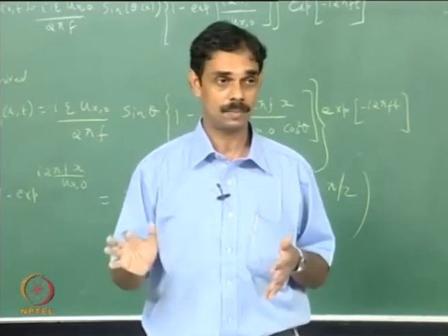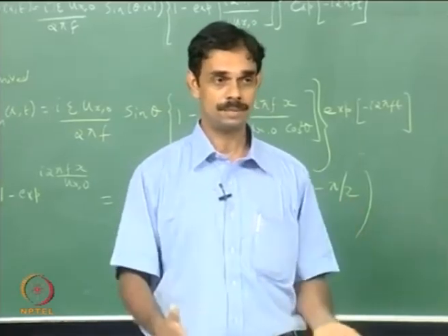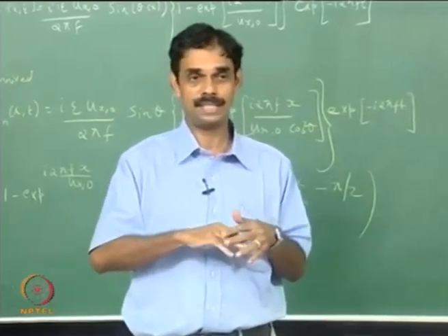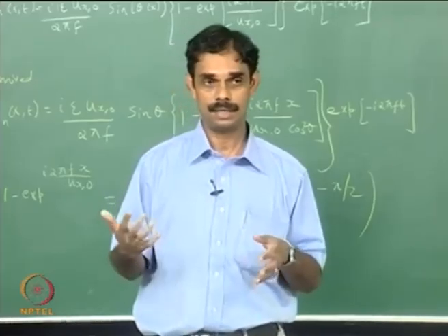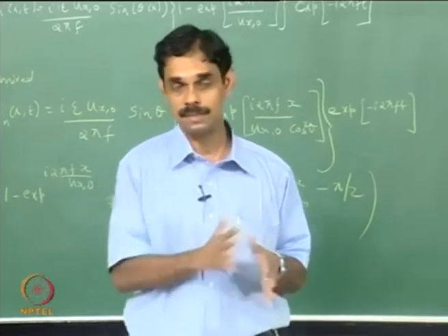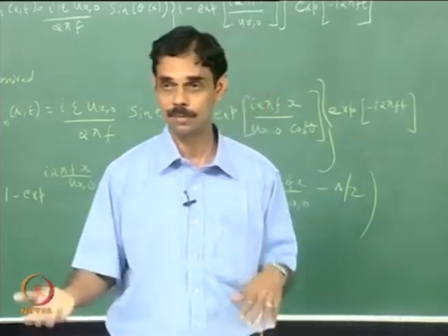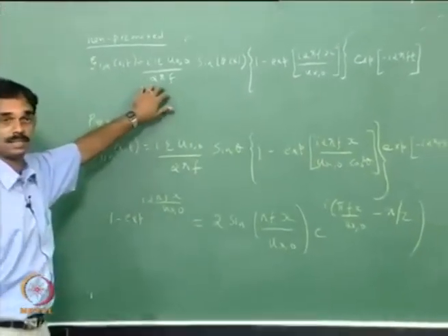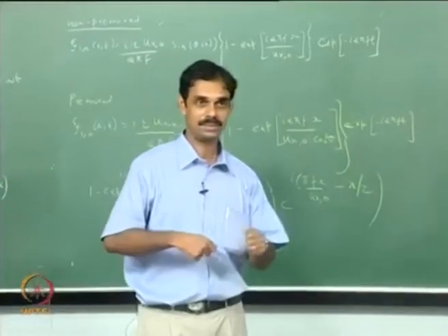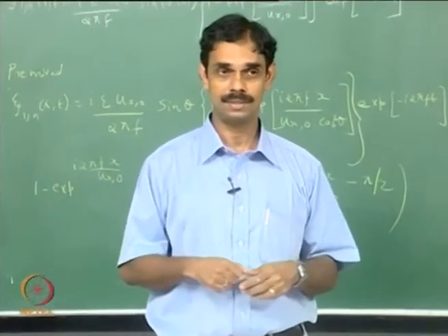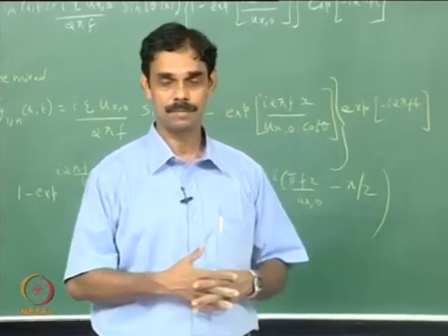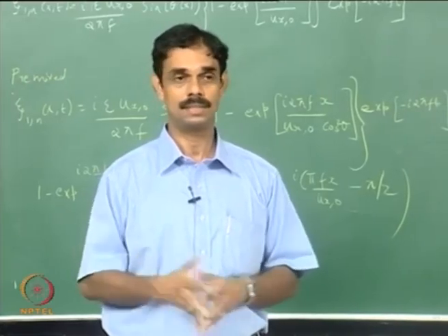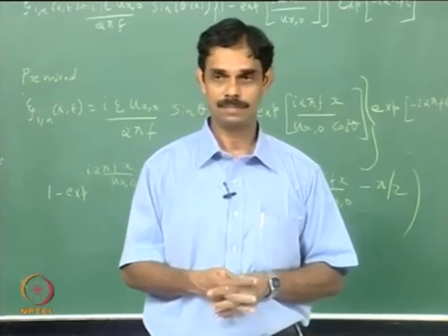Then we calculated how the flame is responding, and the flame response also behaves in a very similar way to the premixed flame, that is you have a spatial pattern which is moving. But the difference is that here it is only the convection, because the flame itself is not propagating, whereas the premixed flame is propagating, so that shows some difference. So you can see in these two expressions the commonalities and the differences. This is a good exercise to help you solve things mathematically. Of course this is a simple problem, and you can try more complicated things. Everything may not be analytically tractable, but then you can solve things numerically, and this will be a simple benchmark problem.